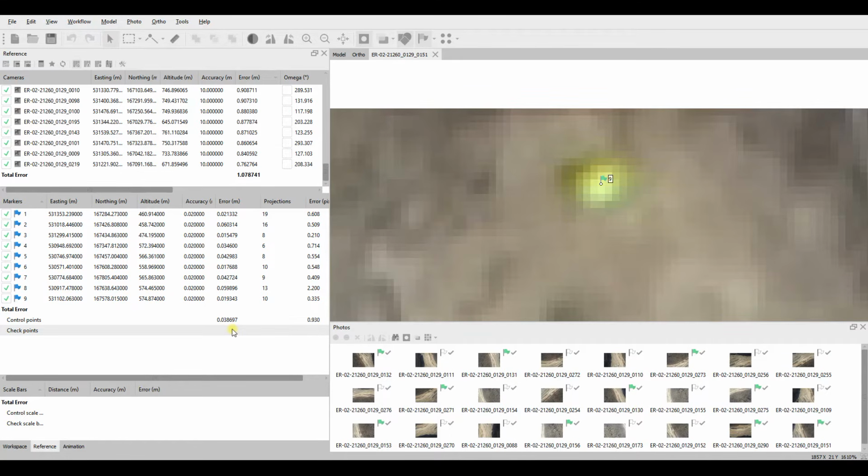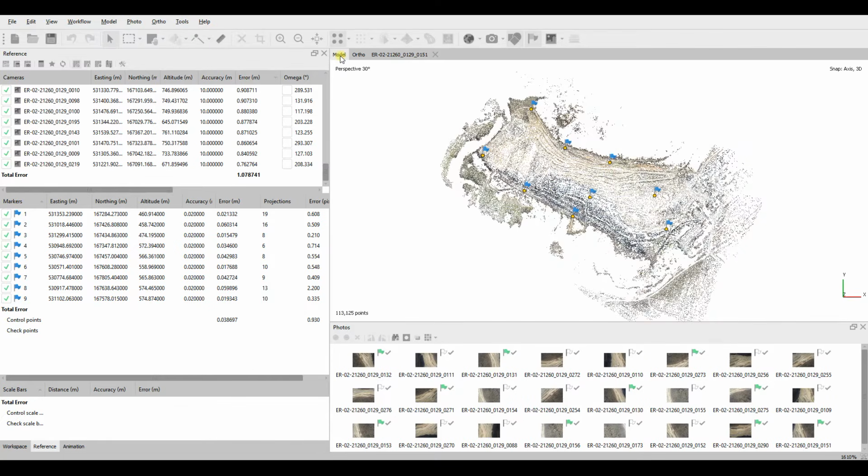So what we need to be aware of is that the software will always do its very best to come to a zero-sum solution. The software is just trying to reduce the error. It's not really paying attention to best survey practice or photogrammetric principles. It's using mathematics to reduce the error as best it can. So if I take a control point and I'm going to adjust it, manipulate it by 20 centimeters now, and I want to show you the danger of leaving those values too low.